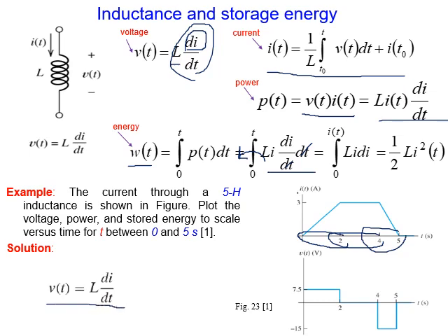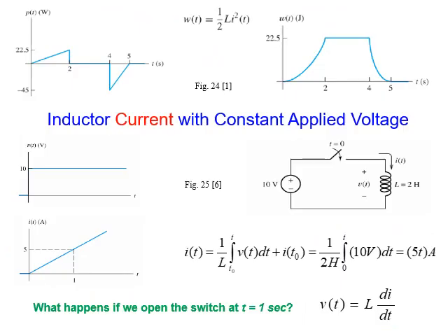Okay, here the current is given to me. So differentiate. But first we need to represent this figure by a formula. We represent it and then we differentiate with respect to time, multiplied by L, to give you the voltage, as you can see here in this formula. After that, current multiplied by voltage, what does it give me? You will say it gives power, yeah, correct?